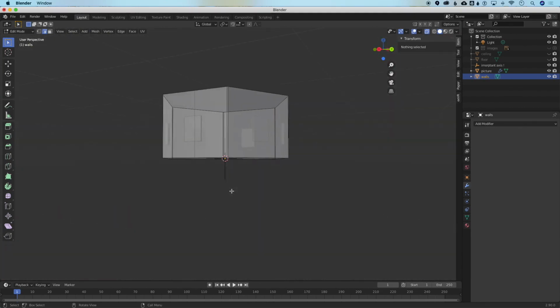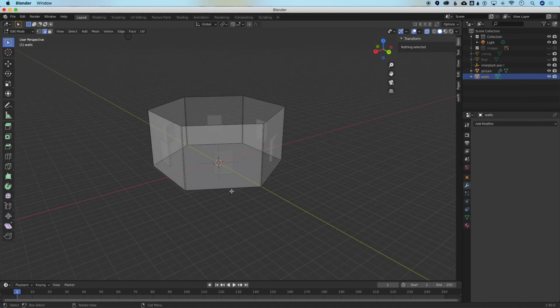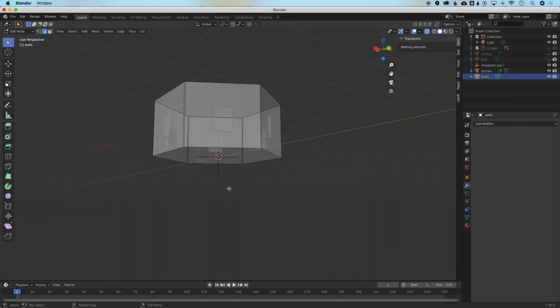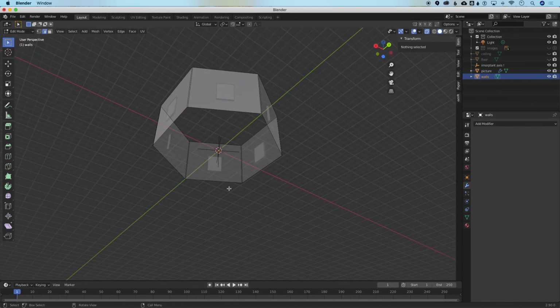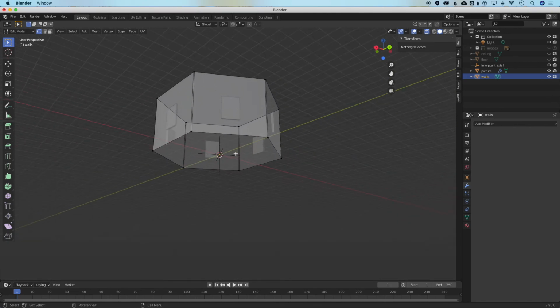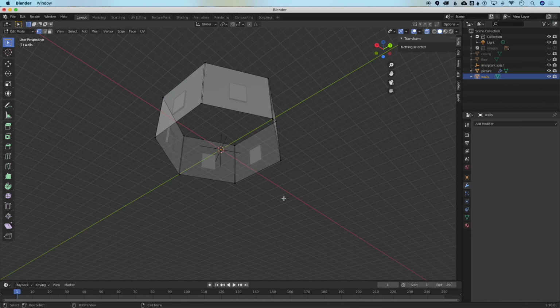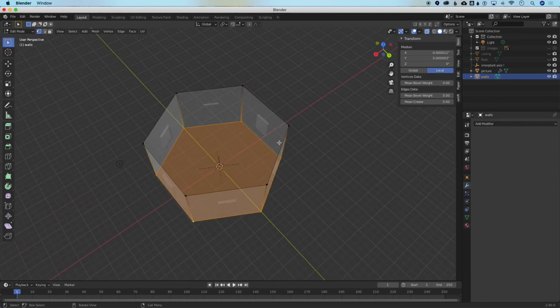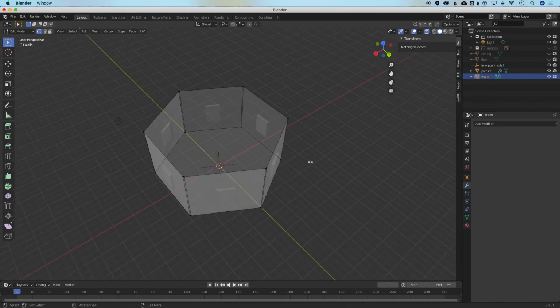If we want to remake the floor with the same bevel, we can do that. I would hit 1, select points again. I would select in this, we're going to call it a circle, even though it's a hexagon with extra points in the corners. We'll call it a loop. I'll select between these points and press Option or Alt and click, and you can see it'll follow this path. And then I would press the F key, and I've created a new floor.